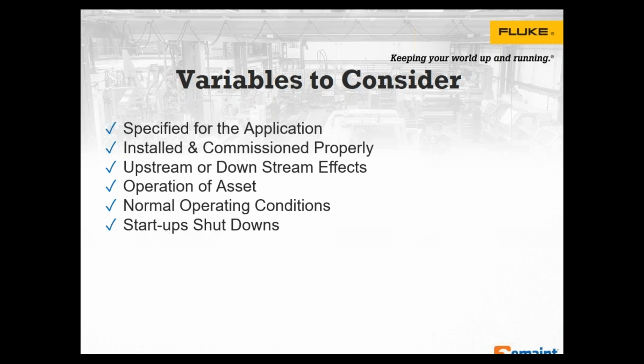If it's on a temperature control circuit or flow control circuit, maybe they have a proportional band type controller, there's overshoot and undershoot. Those are things to consider. Is it right after startup? The same thing applies on a shutdown. Now, it's not so much important on the shutdown itself, it's understanding what happens after a shutdown.